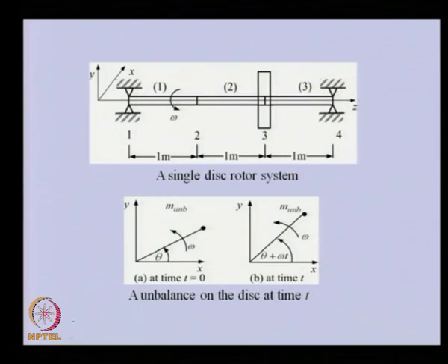In this particular case, because we are considering the unbalance which will be acting in 2 planes, we are considering the motion in 2 planes x and y. As such, there is no coupling in the 2 planes because bearings are rigid, but still for illustration purposes we are combining the 2 plane motion now.